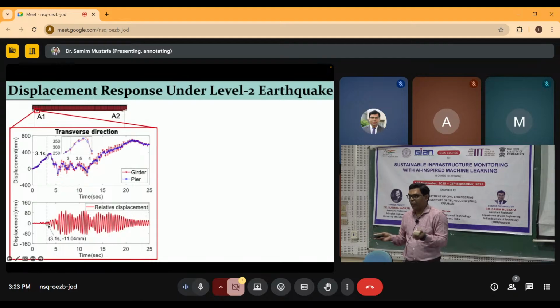So why is it designed to fracture? Because we also want to dissipate some energy. We are allowing something to get damaged. When there is damage, it also dissipates energy by going into damage mode, right? Otherwise, if you do not allow it to fracture, what will happen? It will try to resist, and whenever something tries to resist, there is accumulation of stress. So stress will be very large, and probably failure of the bearing could also occur. To prevent that, we allow the side block to be broken in excess ground motion.